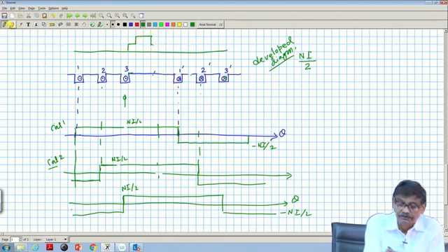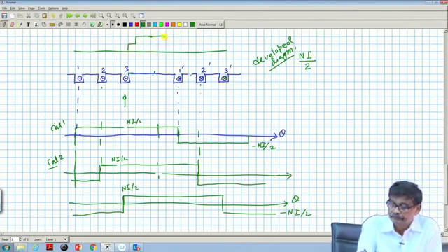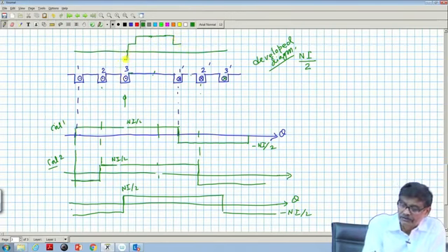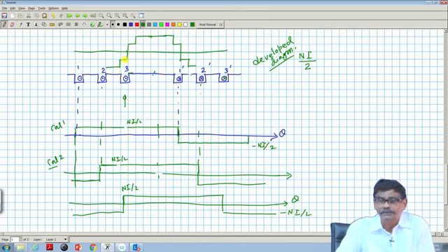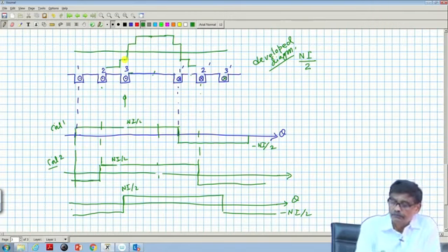It will continue the maximum value up to this point and so on, and this side also it will be like this. It will be a stepped waveform, we know that. Got the point. Therefore, the resultant field waveform will be stepped and the peak will occur here at the middle point of 3 and 1 dashed.